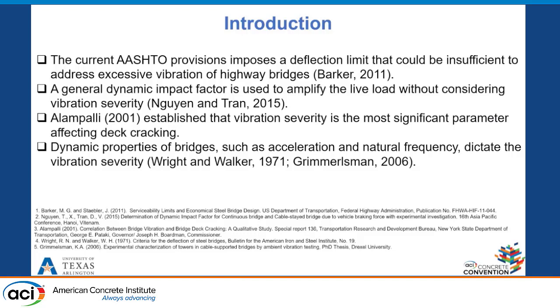Furthermore, it's been established that vibration severity, quantified by the peak acceleration of highway bridge components during regular traffic flow, is the most significant parameter affecting deck cracking for long-span bridges. The current condition of highway bridges can be assessed by obtaining the dynamic properties such as acceleration, natural frequencies, and mode shapes.